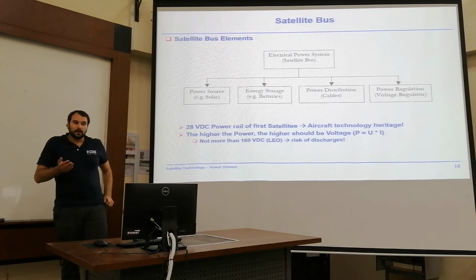So for most cases, everything but the heaters and the sun sensors on the lower right, they go on minus 30 volts, I guess. Those other components are fed with unregulated power of up to 70 volts, and have their own power box that regulates the power for the unit. So you can distribute your power unregulated and then have several units take care of the power conditioning.